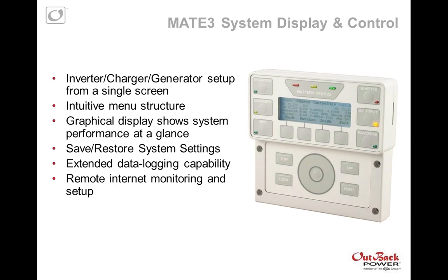With a gigabyte of memory, you can record probably a year's worth of information, which is probably more than you'd want to deal with. However, I always recommend that whenever you commission the system, you also turn on the data logs, because that's the time when the customer is still learning the system and system optimization is still happening. It's nice to have those data logs. So if there are a few bumps when the system's first up and running, you can go in and look at the system and see what's going on.